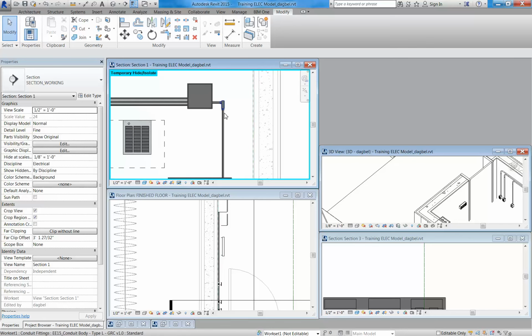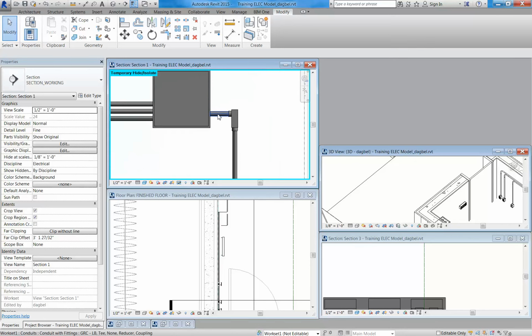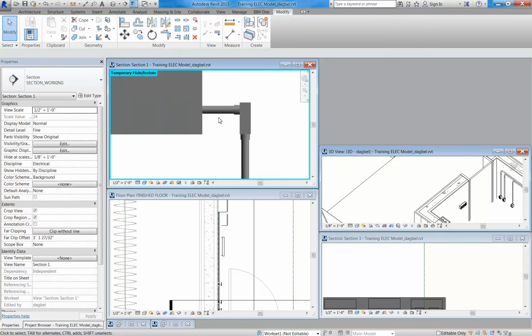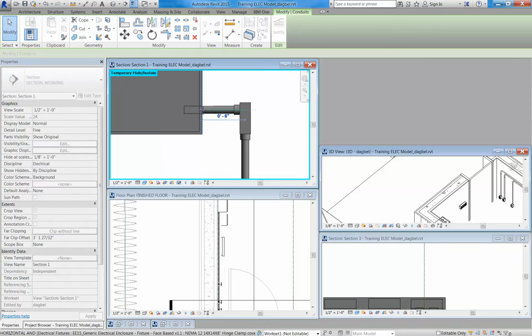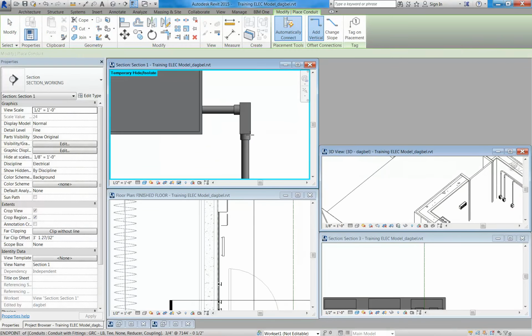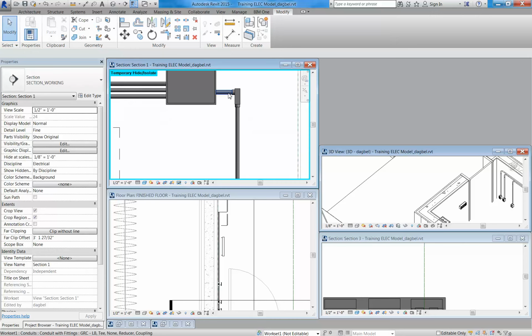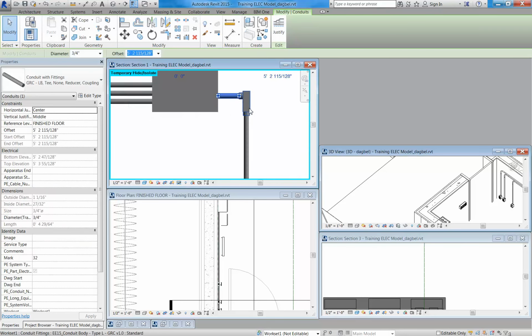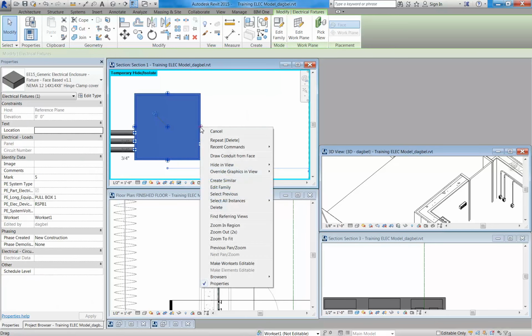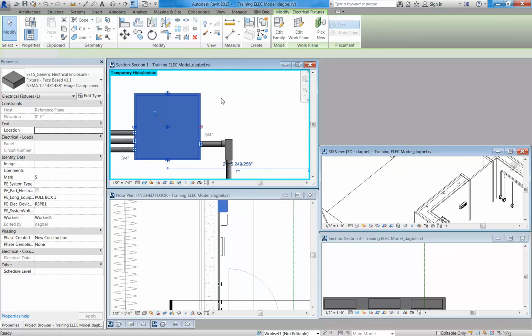If you notice, if we disconnect this one and then try to reconnect it, it's going to redraw this conduit from this direction into this direction, and that starts on a horizontal run, so you'll get a horizontally oriented fitting. Or not. Sometimes it does, sometimes it doesn't. If, however, we tried to draw in this direction.